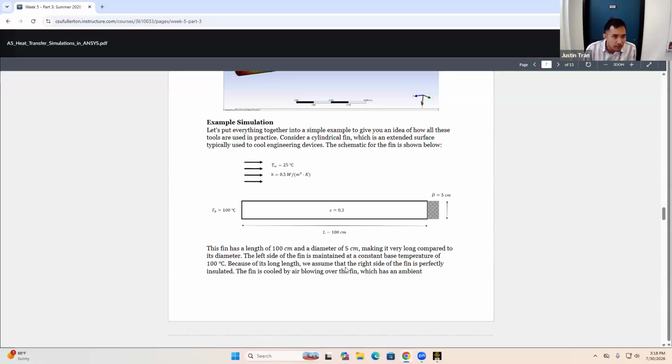If you're going to have significant temperature variations where one section of your part will be much hotter than the other one, you may have to couple the simulation. So you may run a thermal simulation and couple that together with the structural, so that point by point it can compute the temperature and then more dynamically compute what the material property is going to be based on that temperature. So there's a way to do that as well. It shouldn't be too expensive because both structures and thermal are fairly cheap simulations. It's not like fluids. And so it shouldn't be too hard to set up.